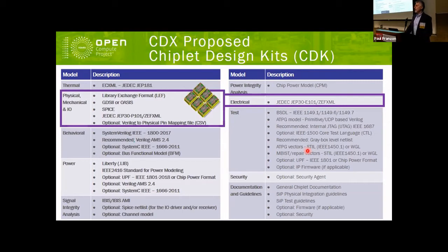So we're just looking for the top level information, the pins and the layers that they're associated with that are relative to the packaging and integration. Now, the LEF models are used by EDA tools, and the traditional LEF models that are used for ASIC tend to be more targeted for place and route. So they may not be directly applicable for use. So we may need to develop what I call a package LEF model, which is more appropriate for package assembly.